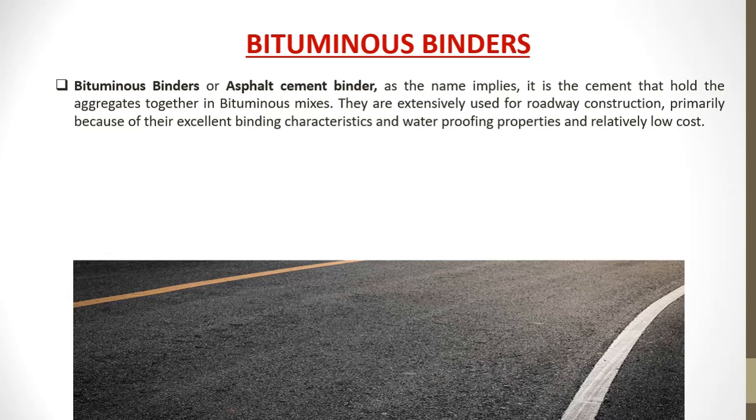These bituminous binders are extensively used for roadway construction and also for airport runway construction. Why? Because they have excellent binding characteristics. It's an excellent glue, and it has waterproofing characteristics. As you know, our road should be waterproof, otherwise it will damage the road. So it has good waterproofing characteristics. Also, the cost is low.